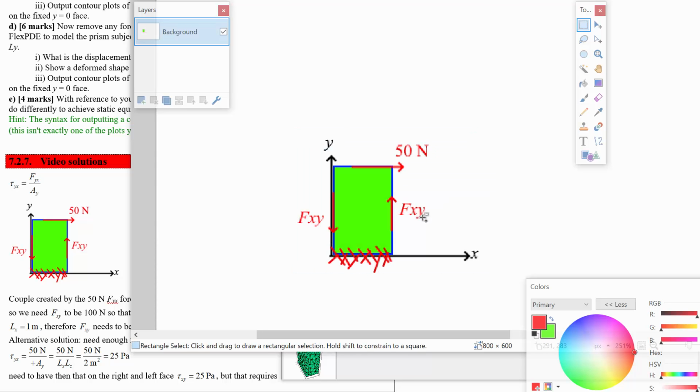I think the last things I drew, oh, good. Okay, so if we cancel those forces, then the bottom fixed support will have to put a 50 Newton force here and a moment on the bottom, which is enough to cancel the 100 Newton meters, right? So this is itself 100 Newton meters, but in the opposite direction to the moment created by those two forces.